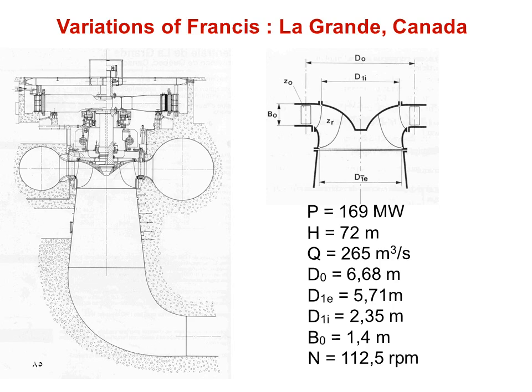Its power output is about 170 megawatt, works under head 72 meters and discharge 265 meter cube per second, and its outer diameter is about 6.7 meter, and the height of the blades at the outer guide vane itself equals 0.4 meter, and the RPM equals more than 100 RPM.